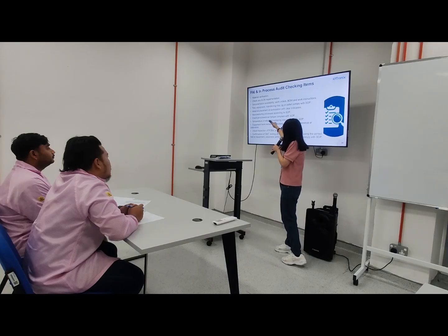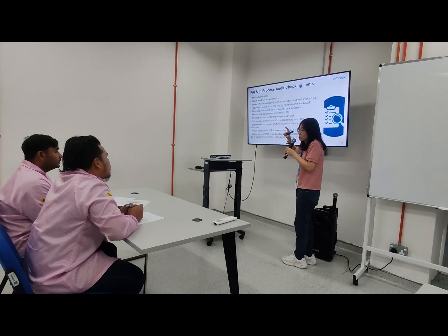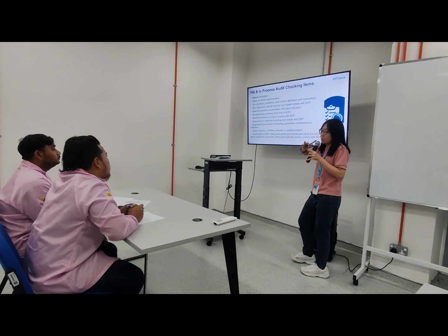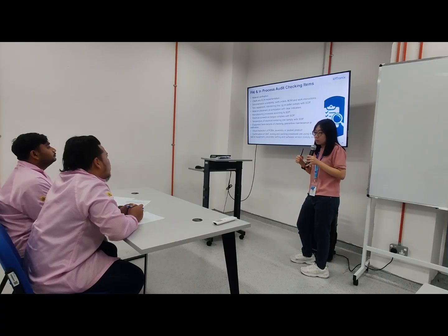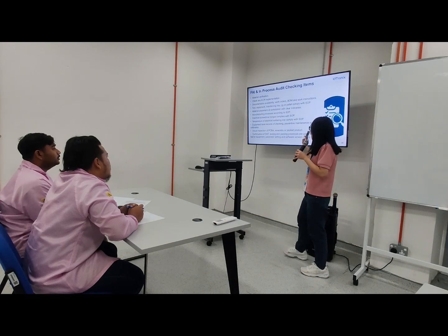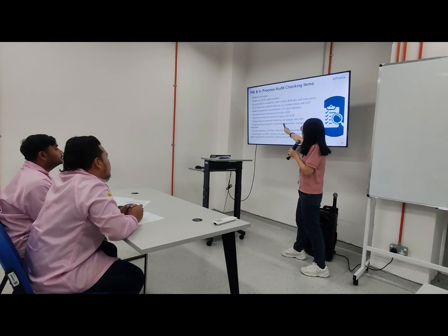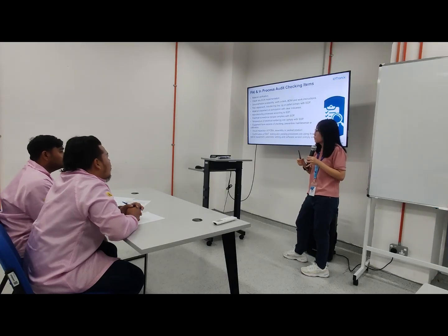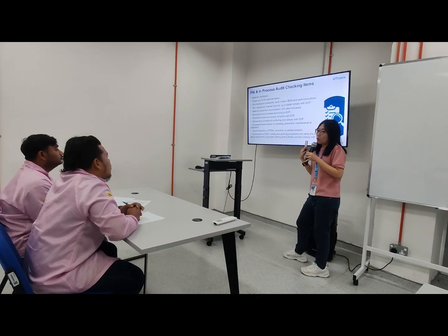Okay. Next will be electrical screw torque. We check whether the torque that we use is the same as the spec set in the SOP or not. And then production needs to have a daily check on the screw torque with the torque checker before they start production. Next will be the temperature of the electrical soldering iron. We need to check the temperature. There is equipment to check the temperature of the soldering iron, and the equipment might have records of PM or calibration checking.